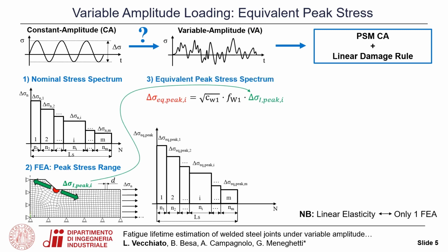At this point, for each nominal stress range, it is possible to compute the equivalent peak stress range and obtain the stress spectrum in terms of equivalent peak stresses. Please note that for its evaluation, only one linear elastic finite element analysis is required.